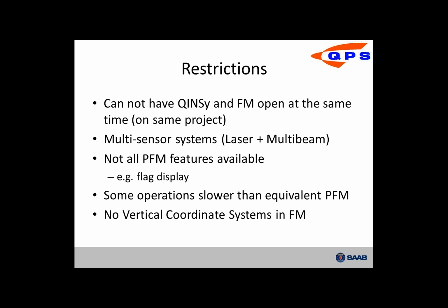So if you have a multi-sensor system that is, for example, dual head multibeam, multiple multibeam, that's fine. It's when you want to exclude one of your systems from your navigation surface. Right now, Fledermaus does not have any ability to know that you've excluded one of those systems. So when you do edits and you do recubing, it's going to bring back in all the data from all the sensors. We'll be addressing that very shortly in one of our upcoming releases.